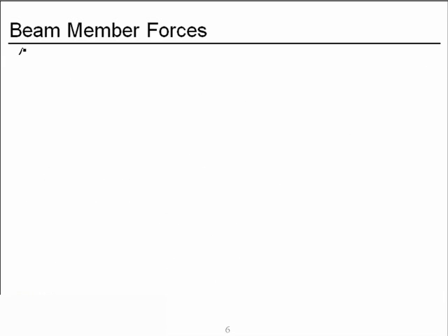Now let's assemble the structure stiffness matrix. The structure stiffness matrix is given by capital K, and it'll be the sum of little k1 and little k2. But I want to point out, it's not just a 4x4 matrix. This summation is by degree of freedom. So capital K will be a 6x6 matrix.